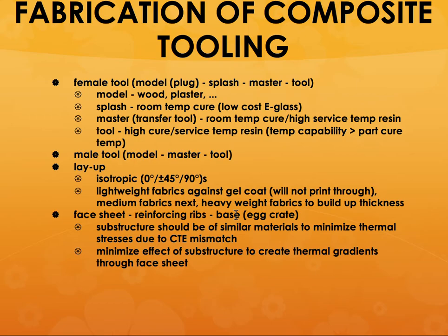if it is a huge part like a wing structure or a ducting structure, just imagine the weight of the tooling itself. Tooling can be in the tons weight. So the whole tooling has to be moved with a crane, a mechanized crane. And then after the part is laid up, you have to move the whole thing into the furnace. And then after the part is cured, you have to remove the whole thing. And then you have to have some way of removing the part from the tooling itself. So the lighter the tooling, the better.